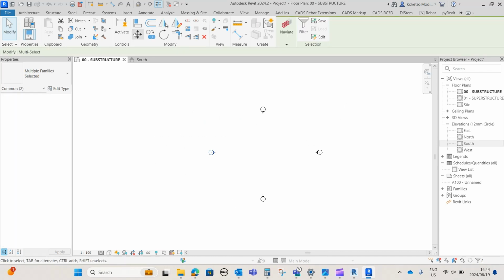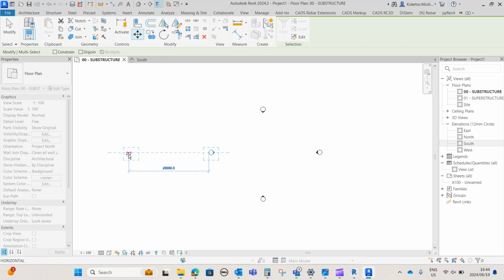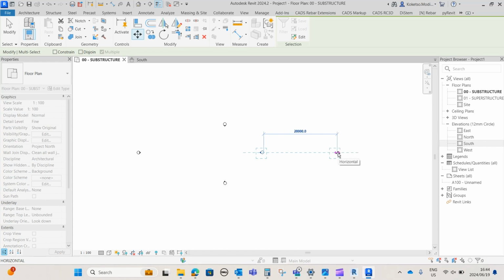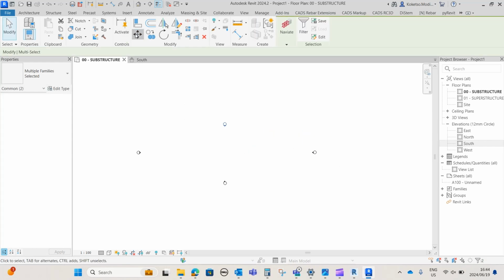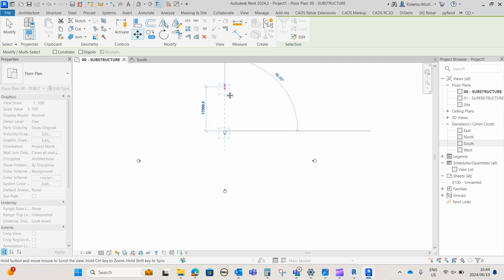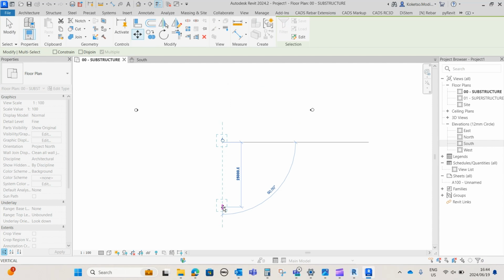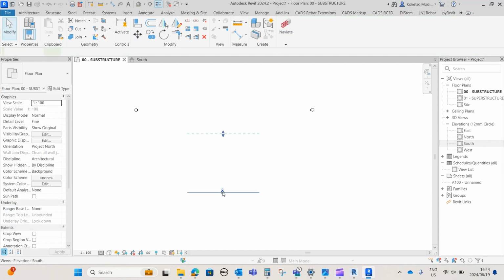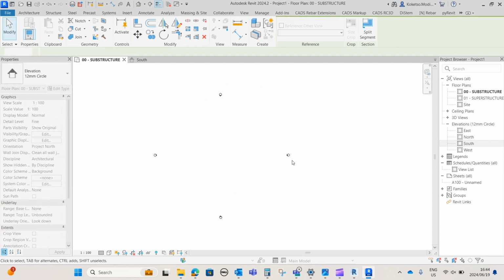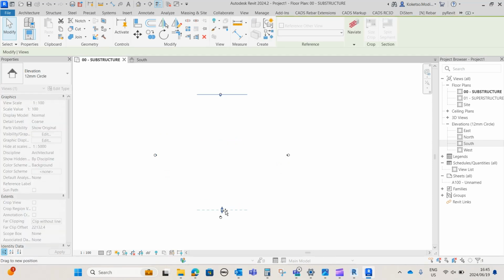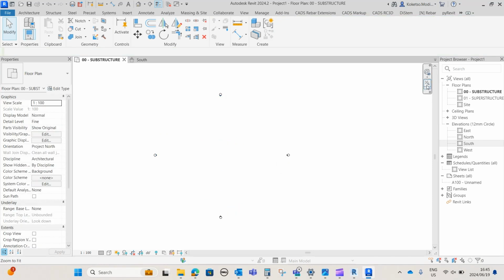So in the substructure, I'm just going to extend the views and I'm going to offset them by 20,000 on each side. And also this side, I'm just going to offset them by 20,000. And also this side, I'm just going to offset them by 20,000. And then I'm just going to extend their views so that we can view the entire project when we model within these constraints. So I'm going to select these views and then extend their view range.